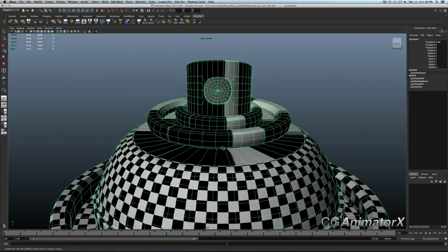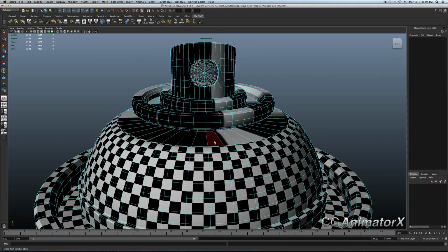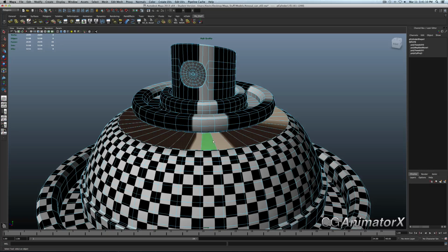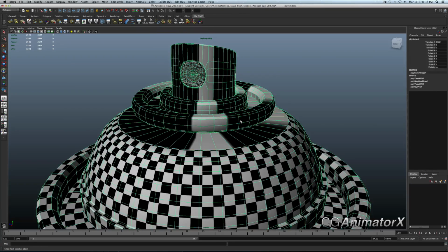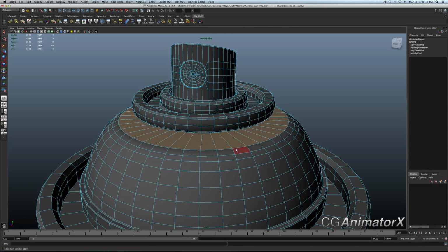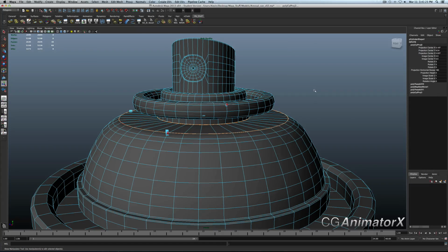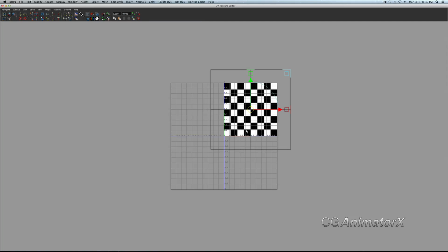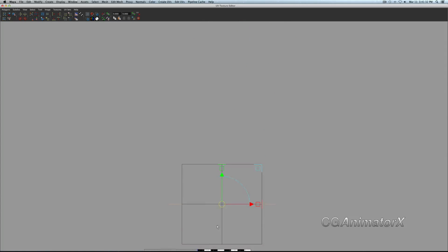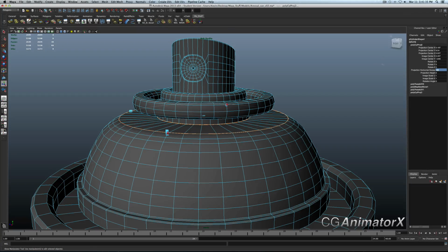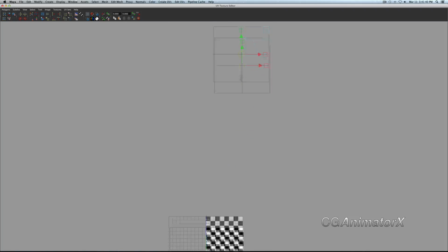All right, so we're getting closer to the end. So there is light at the end of the tunnel. Select these, create UVs, cylindrical unwrap, project, 360. Nope. Change that to 180, so when you projection horizontal sweep, leave it at 180. It's usually those flat surfaces that don't respond well to that.